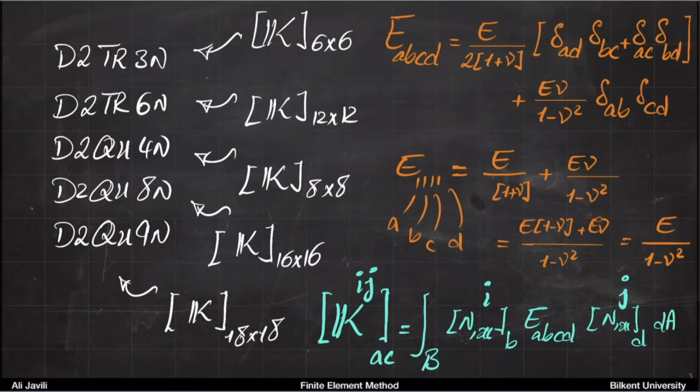So incompressibility is 1. Usually Poisson ratio goes to 1/2, but in a plane strain case, because it has this degenerated definition, it's a fictitious definition basically. So this is not the real Poisson ratio of the material. The 3D Poisson ratio is maximum 0.5.